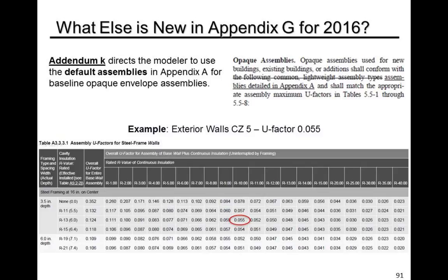It's a steel frame wall, 2 by 4 inch deep steel stud, 16 inches on center. It's nominal 4 inch, but they're actually 3.5 inches, with R10 rigid insulation and R13 batt insulation between the studs. That's your construction and it gives you the U factor of 0.55 that the standard is asking for.